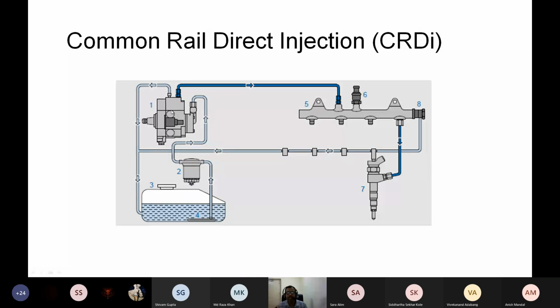That is possible because this pump is a piston assembly kind of pump. So if you require a lower pressure, then we are not going to compress the fuel up to the maximum stroke length, and the opening of the fuel is going to be open much earlier, before the piston in the pump reaches the top dead center.